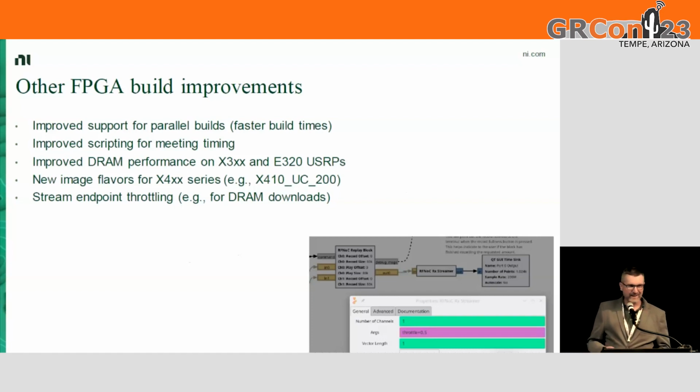One fun little thing that we noticed is if we produce data at line rate on a 10 gigabit Ethernet link, so we send data from a USRP into a computer at line rate without any interruptions, back-to-back packets, NICs, as in network interface cards, won't always be able to keep up. So even if you have a reasonably powerful computer, the network interface might say, oh, I've been dropping packets left and right because I can't quite keep up with the data rate that's coming out. And this is nothing that we can catch with our flow control.